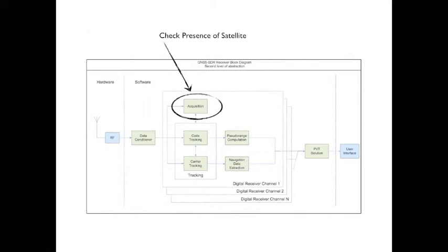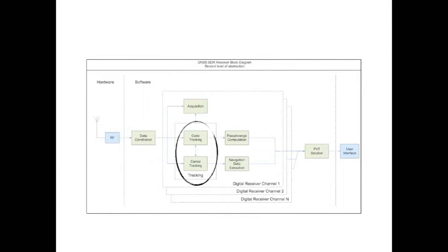Once a satellite signal has been detected, it has to be tracked. We need to track basically two values: the carrier frequency and the phase of the PRN code. The frequency of the carrier changes during time because of the Doppler effect caused by satellites and receiver movement. The PRN code, which is used to identify uniquely each satellite signal, varies in phase when the distance between the satellite and the receiver changes.